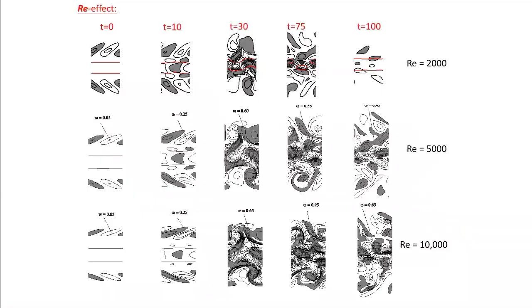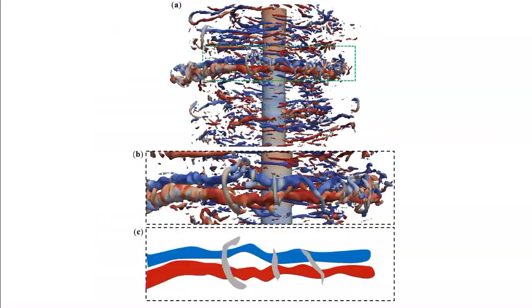This is interesting. This is an additional study on how this is important, particularly as you increase Reynolds number, these dynamics become much more complex. And there are many details on this work, which again, I will not go into. I will just mention some key results. This is a more recent study where he's using a vortex column, also with a ring, embedded in fine-scale turbulence.